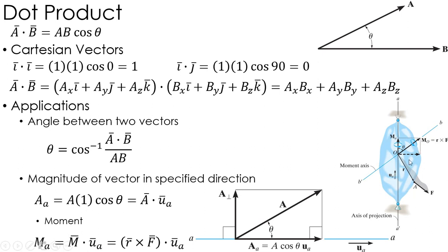So if I take, for example, this, I've got the A-A axis going vertically here. I put some sort of force on it at some point A. I can find the total moment about point O, which actually is along this B axis. And I can simply project that over onto the A axis by doing that dot product.